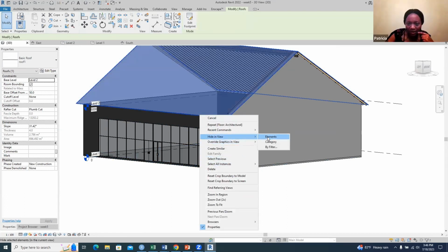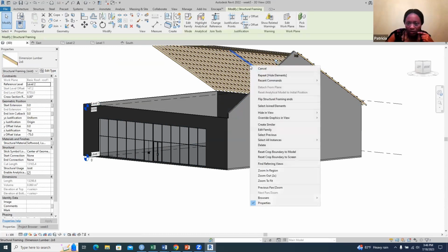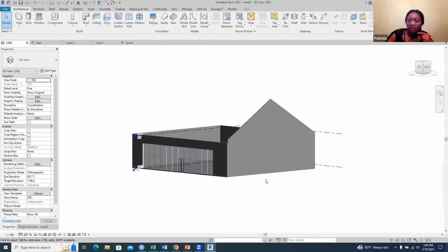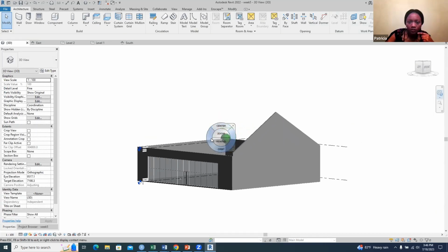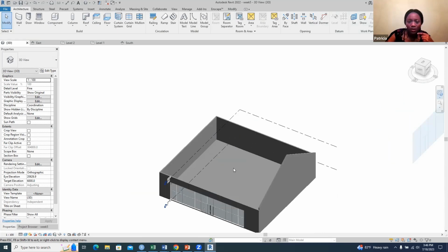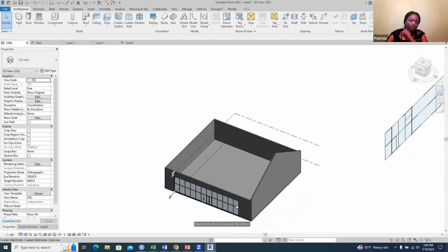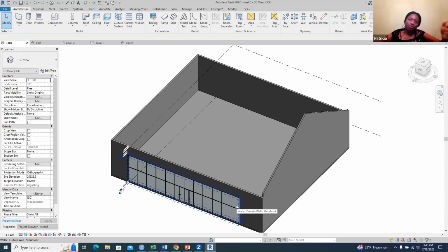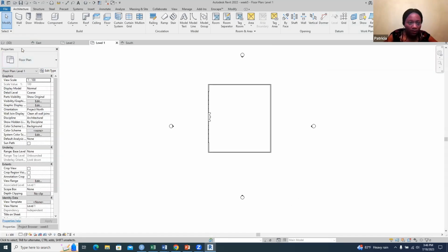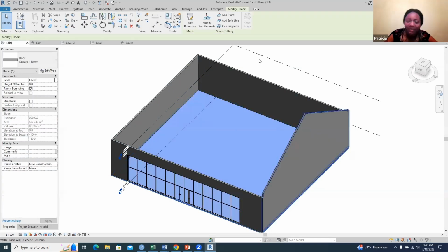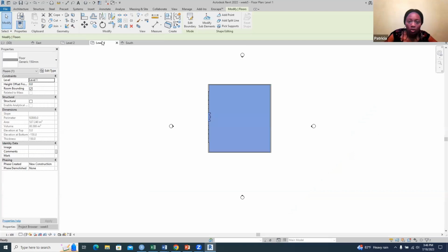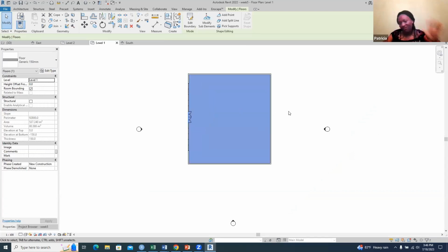Elements, and then if I select all this, hide it by the category, I don't see all that, and then we go to the wheel center. So we have our floor in place now. So let's say you want an opening in the floor. Maybe you want to put an elevator for the ground floor. So we go back to that level. Our floor is there, but it's easier to select it from this 3D. So I selected the floor, and then I go to level 1. Once you select it in any view, it will be selected in any other view that you go to.